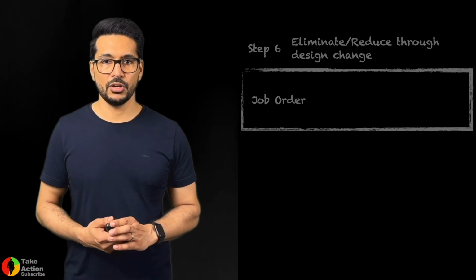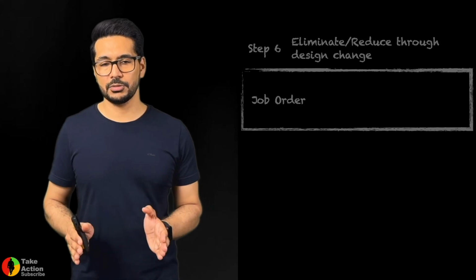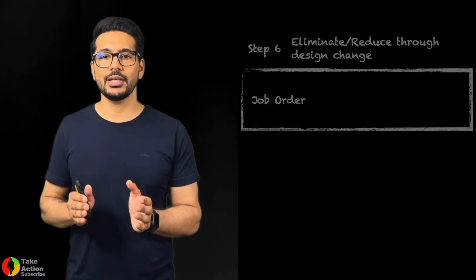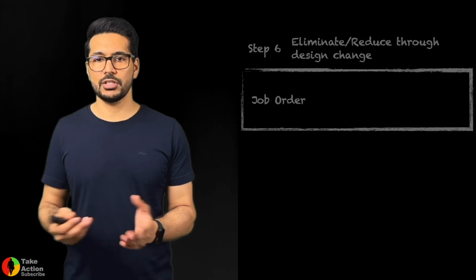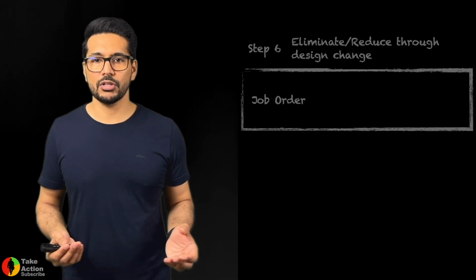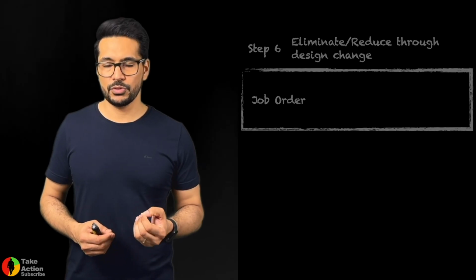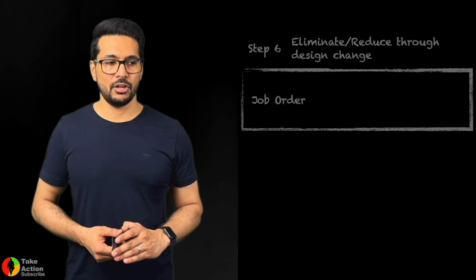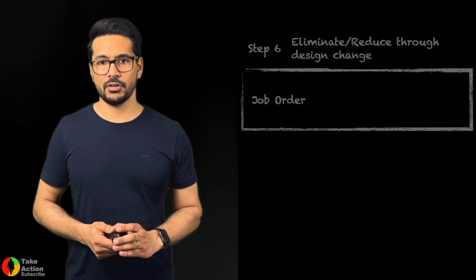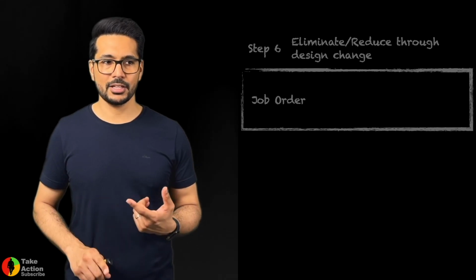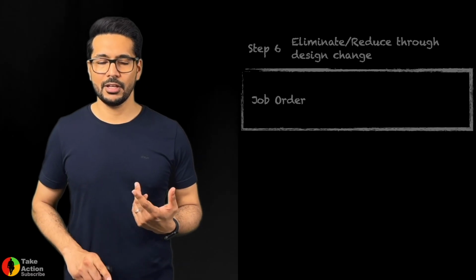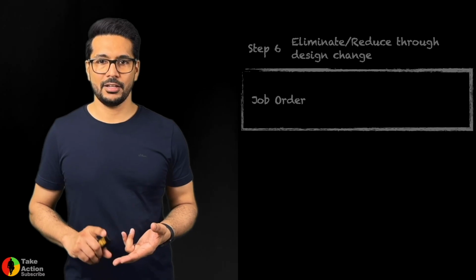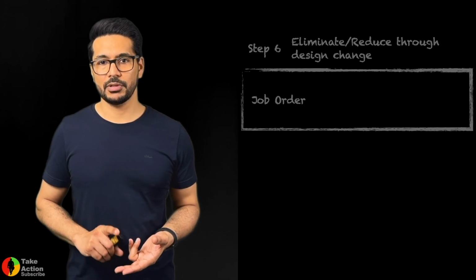So for us, we just had 1 standardized process for 1 assembly with these 2 small inexpensive parts, which in the end increased the cost by just a few cents, but it saved a lot of management effort to maintain different articles and different inventory, and we could reduce a lot of buffer area for the implementation of our Kanban system.